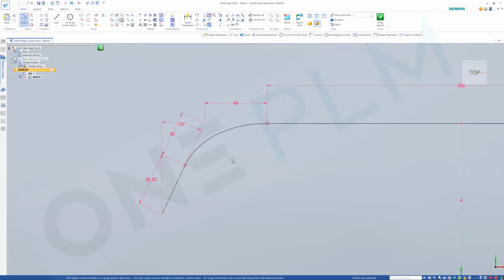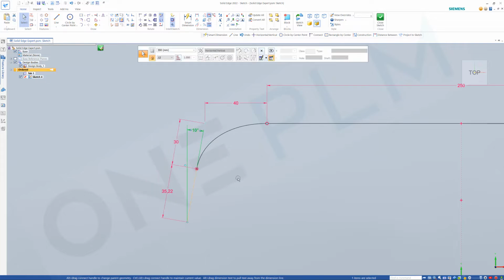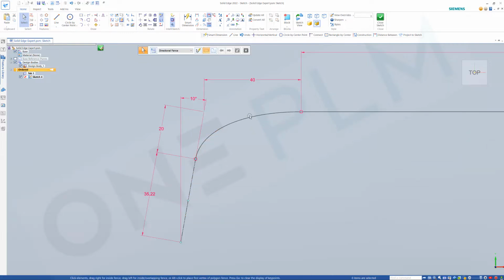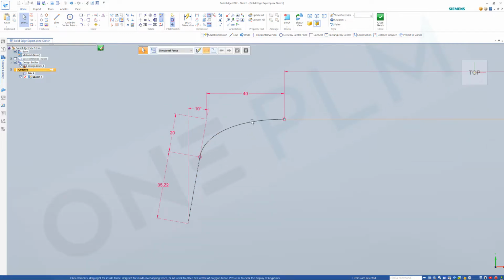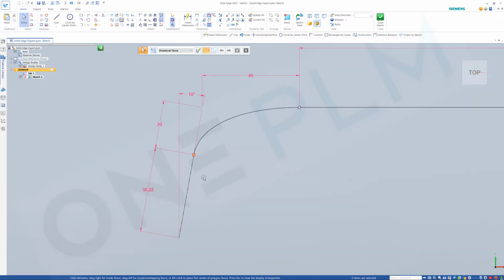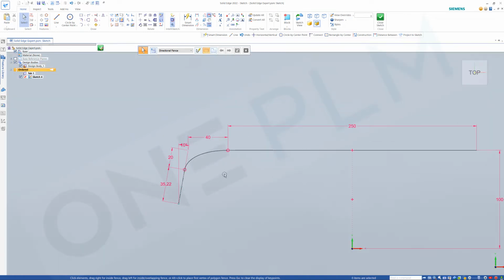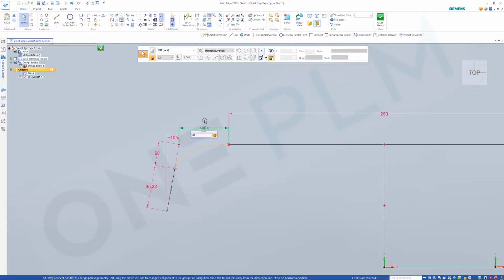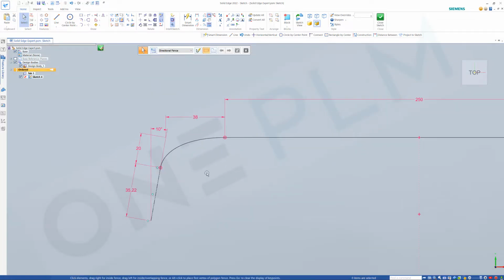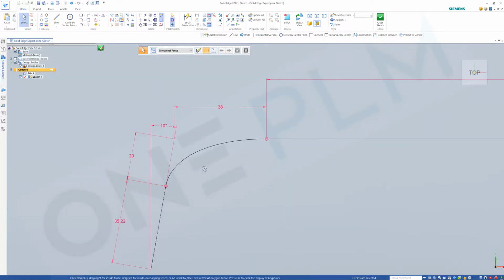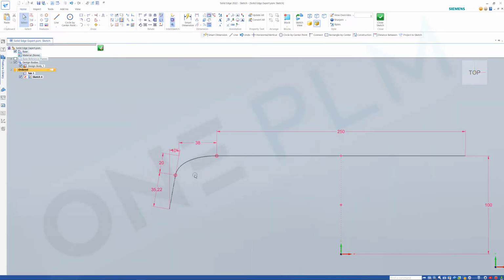If I change this 25 down to 10 degrees, you can see how we've got that tighter sweep up on there. If I change that to 20, you can see how we've got a real progressive curve. So whatever clicks into that position is going to be nice. Obviously, if you want to put it up flat, no problem, we just split this and turn that into a little flat on there, but I want that just to drop straight down into there, and that gives us a real nice option to control and get that exactly the way that we need that on there.